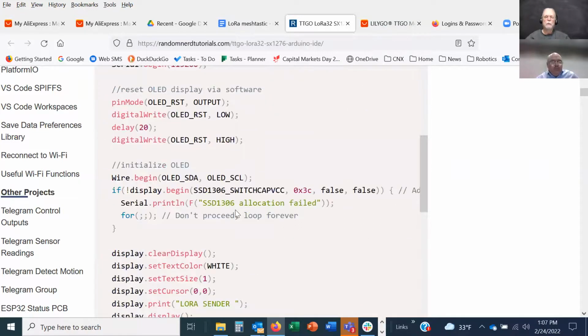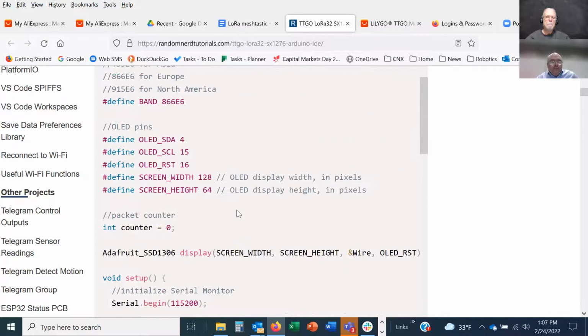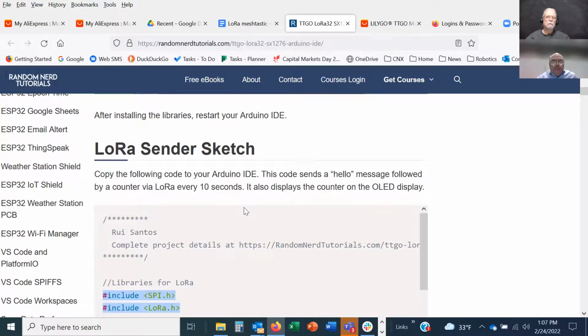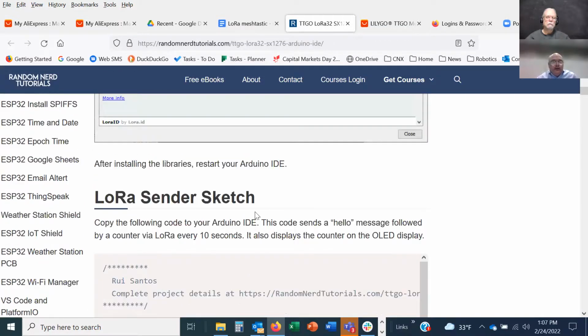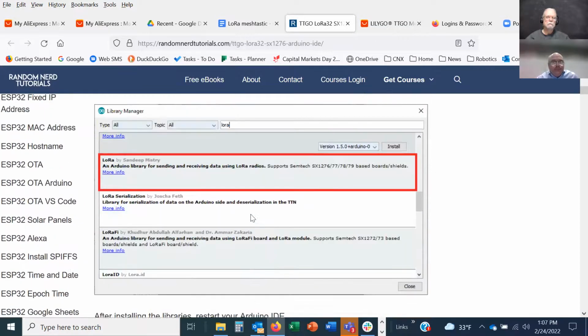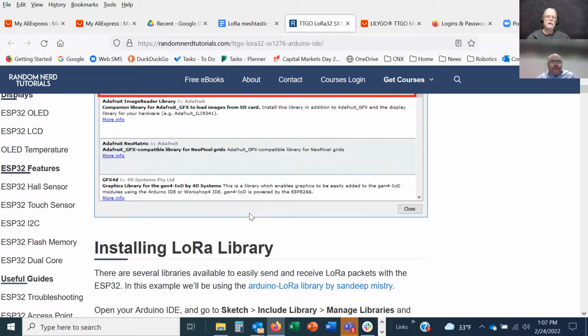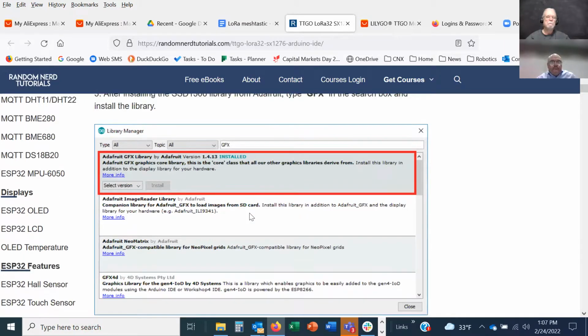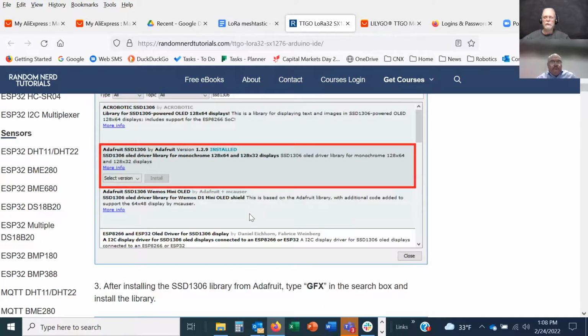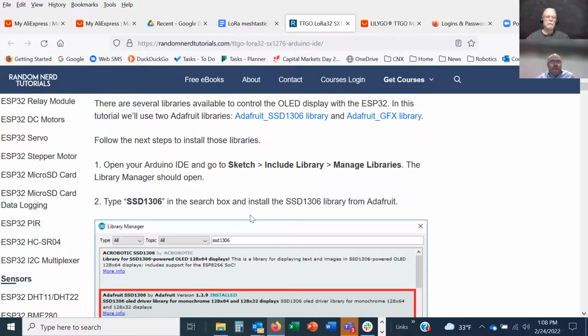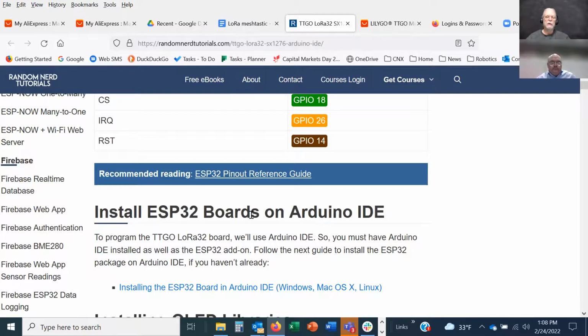Do you know offhand which frequency that was? I had the 915. Okay. Trying to stay out of jail. And I think the 900 megahertz one will either run at 896 or 915. I think you can switch that in software. So if for some reason you would have interference, like a neighbor putting out stuff, you can just flip that in the configuration somewhere.